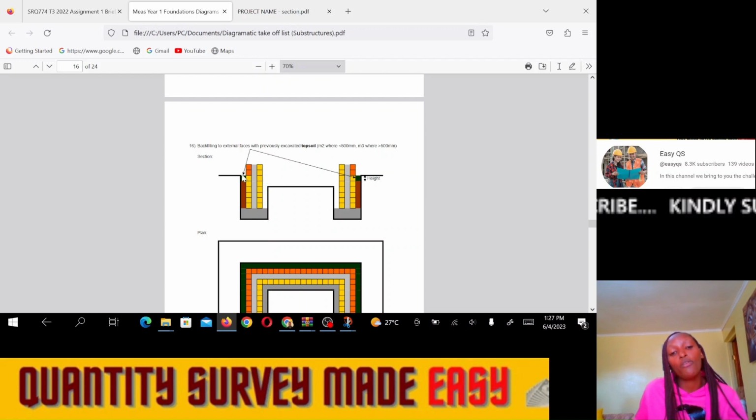But if we were doing paving or continuing in construction, we could backfill it maybe with hardcore, so that it can support the floor here. But now, because you're not told about the construction, you will backfill it with topsoil, and in most videos we call it reinstating the topsoil all around the building, because we need to go back to the ground level after we have constructed the foundation wall.